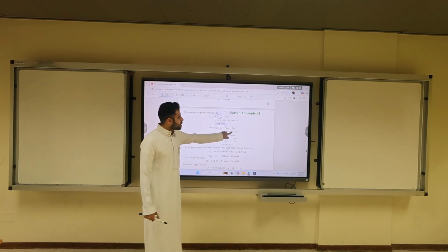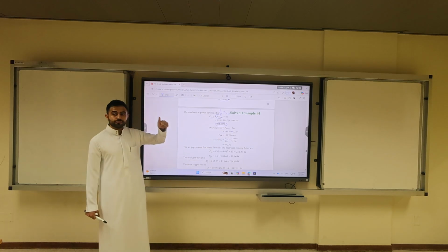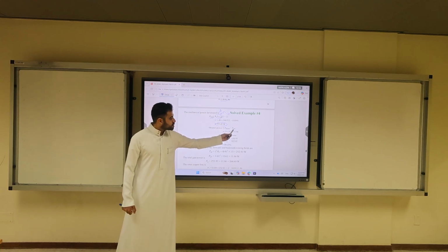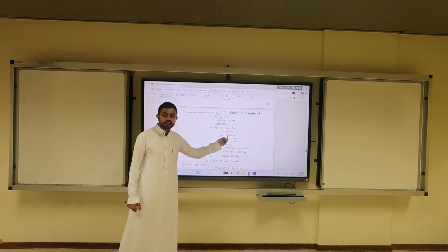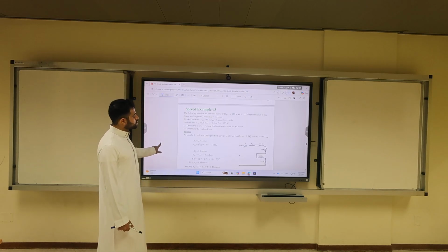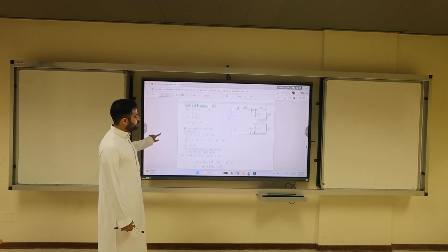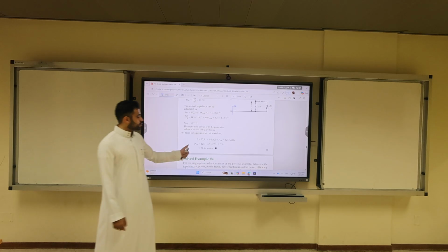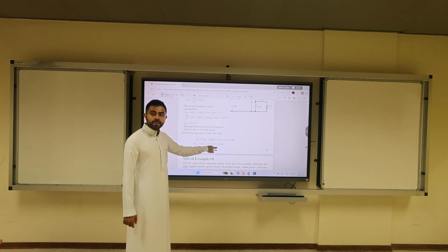The output power, and we said last time, is the mechanical power minus the rotational losses. The rotational losses are found from the previous problem. So the mechanical power is this, minus the rotational power, you get your final output power, which is 158.93. How did we find the rotational losses? From the tests. Rotational losses are usually found from the test, and in the previous example, we found the rotational losses to be from the no-load test minus the copper losses.